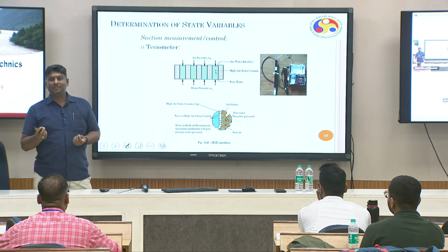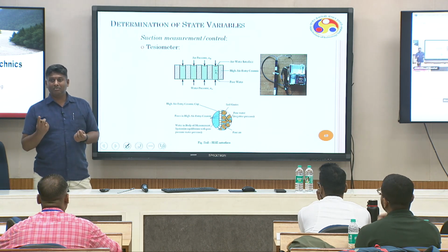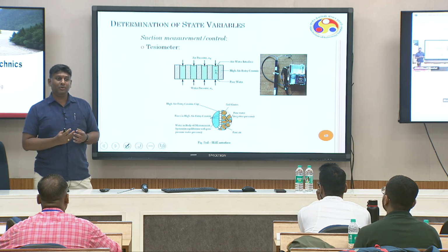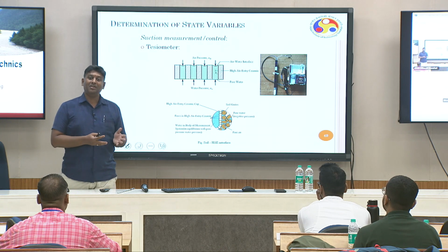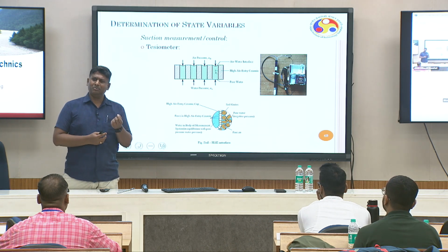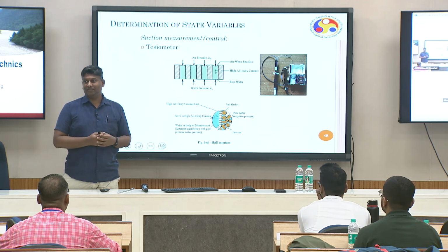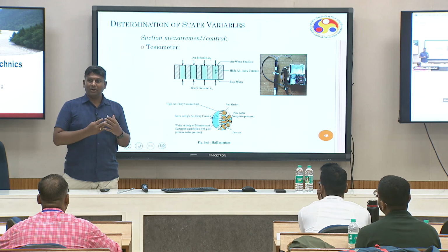That will give an air entry value of 1 bar. 1 bar is 100 kilopascal. Imagine if you want to go for 15 bar, 1500 kilopascal. The pore size should be in the range of 10^-4 mm. Very fine. Beyond that, we can't reduce.